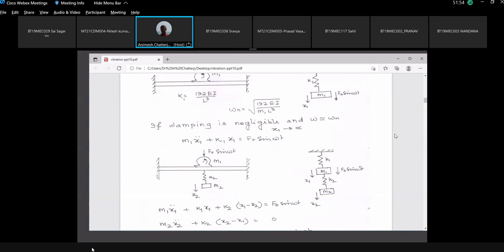Our model where we had only K1, M1, because of this spring, becomes a 2 degree of freedom model, with K2 and M2. So this is my model after I have added this spring. This is called the auxiliary spring, secondary spring or absorber spring. This is called the auxiliary mass, secondary mass or absorber mass. This pair together, a spring K2 with a mass M2, is called the absorber. Fine. So I have added an absorber, and now this becomes 2 degree of freedom.